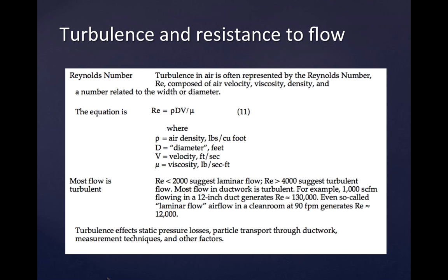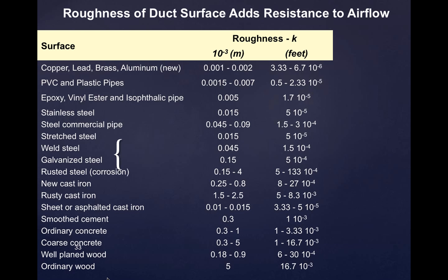Right? Now, when the bottom comes up a little bit and it's shallow, you have a smaller cross-sectional area for that water to go through, or the stream narrows or something like that. Now the velocity has to pick up for that water to flow through it. That area is turbulent. You have white water in those areas. The other areas may be moving very slowly, with very little turbulence. Laminar flow describes flow of a fluid that's almost uniform throughout the fluid, right? And turbulent flow is when you have more and more mixing or friction or changes in direction of the fluid.